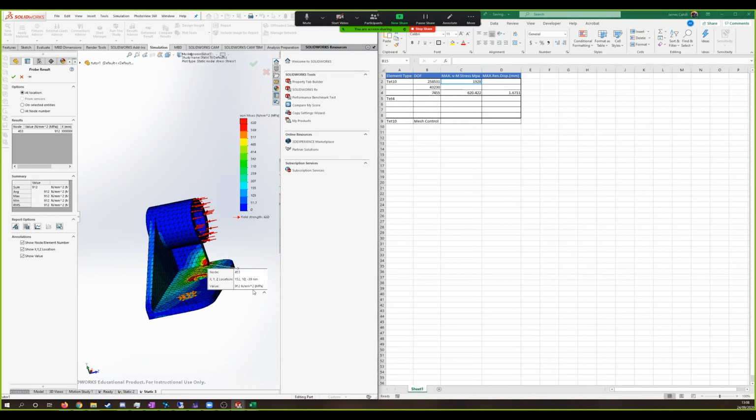How do you know that's the max? Well, you're not interested in the max, you're interested in that spot. Yeah? Because the max can move. If all of a sudden somewhere else on the model becomes higher, the max will move. And you're not interested in wherever the max is, you're interested in the same spot every time you run it. Because you're wondering whether that spot is a singularity.